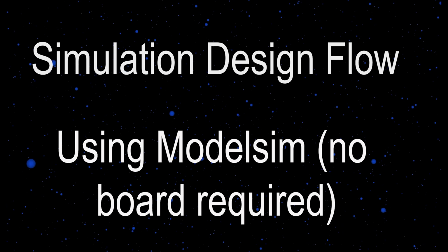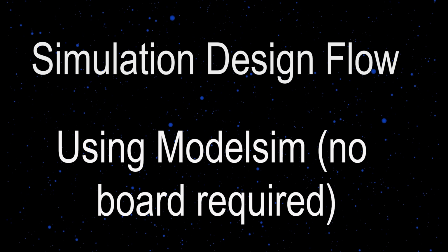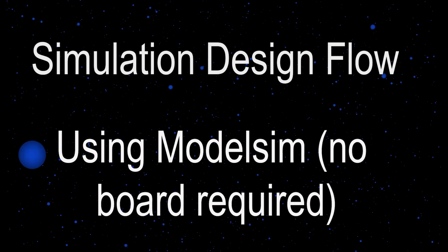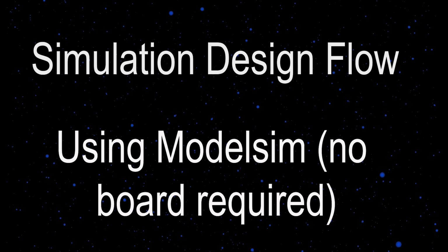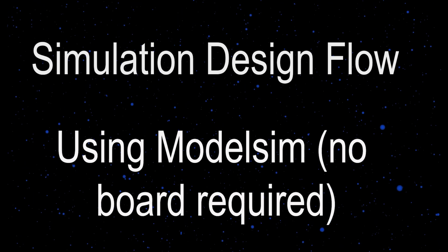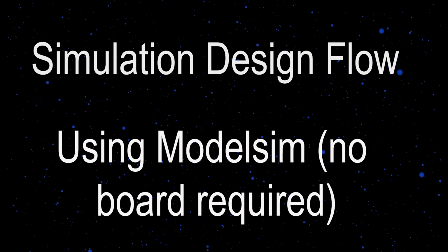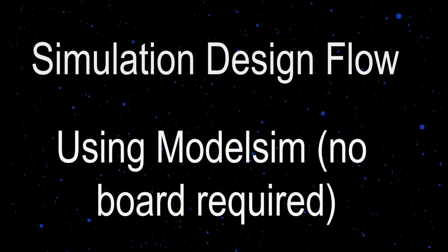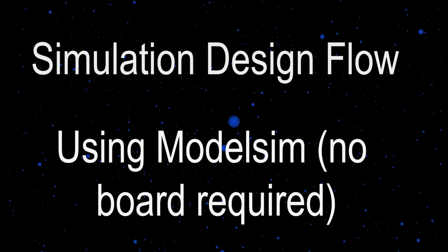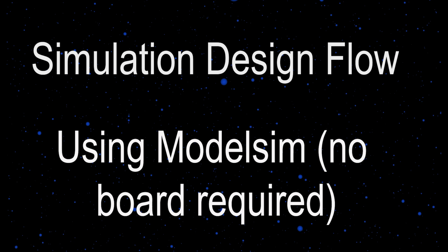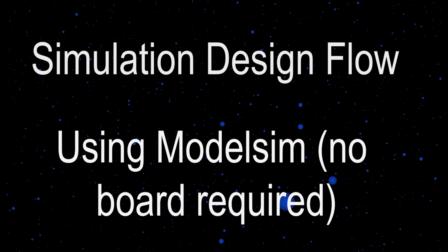Now, if you've seen my previous video on the spectrum analyzer, you'll see how convenient it is to have something like SignalTap for debugging. But the second best thing is to simulate, and it is very possible to simulate a whole design, even with FFTs. But you do run into a problem, and the big problem is, what do you use to actually feed the FFT with? What signal do you use?